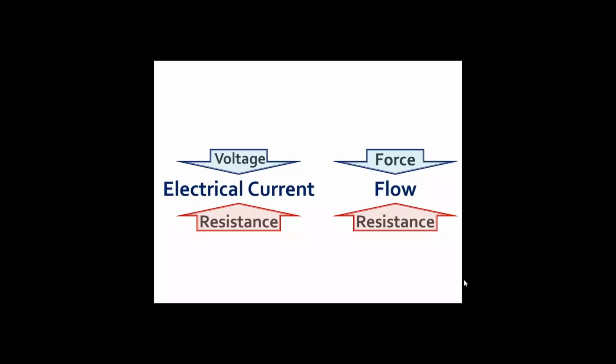So if you exceed that dielectric strength, in other words, you have 10,000 volts that comes in, and you have insulation that's good for 600 volts, you're going to get electrical conduction through that insulation. But it's going to destroy the insulation because it is literally ripping electrons off of the atoms with such a violent force that it's going to destroy the material.